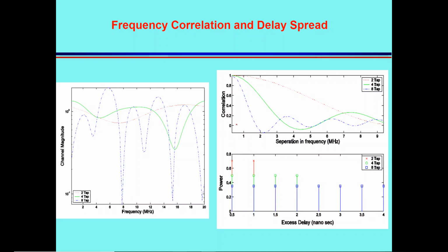What does the autocorrelation function mean at the crossing? At the crossing it's now uncorrelated. As long as it's above zero, it's correlated. After zero, it's independent. So since this has too much variation, automatically the autocorrelation function will have lower coherence bandwidth.